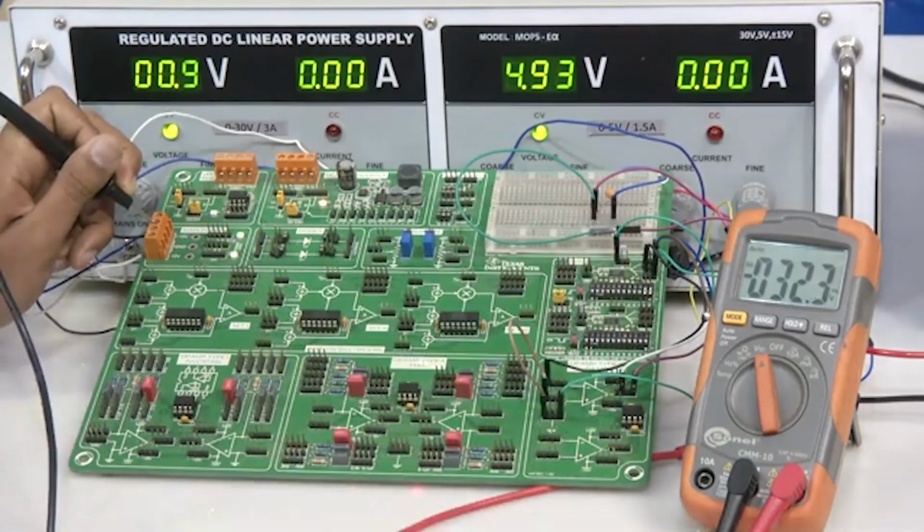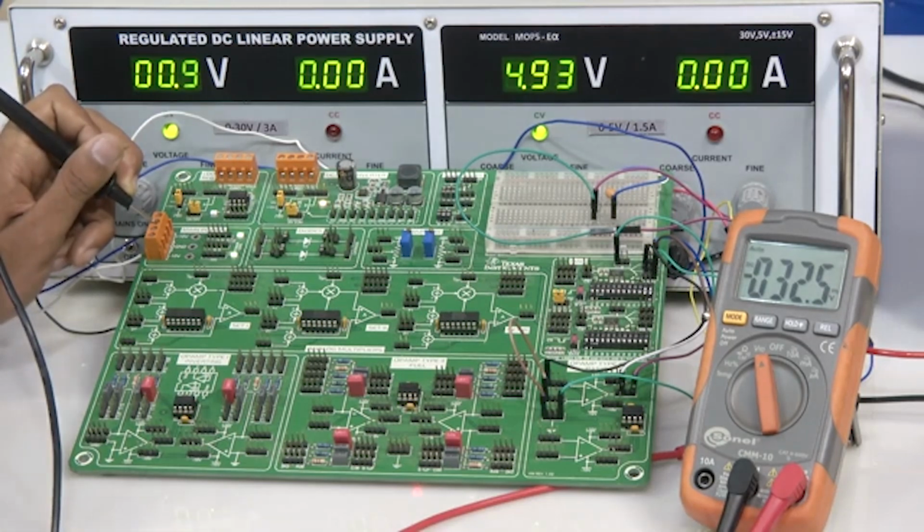To ensure that our circuit design and connections are proper, the best way is to make sure that we are able to predict what voltage we will get when we make a change in the circuit. That shows the robustness of our design. The calculated values might not match, but the curve, the relationship, or the linearity, if at all the relationship is linear, should be maintained. That is what we should look at.